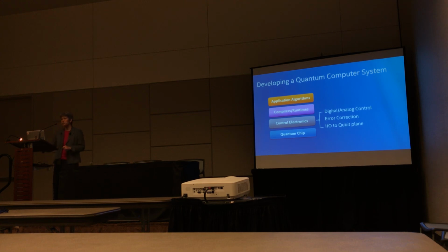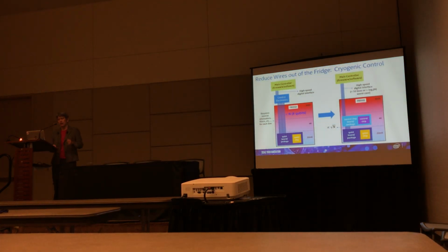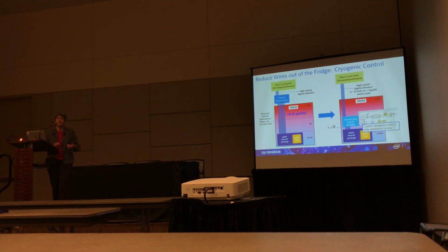So this I/O problem, there are many problems for qubit control, but the I/O problem is a big one. We, as a number of other quantum groups, are looking at bringing the control chip inside the chamber to cryogenic temperatures. The reason is that you need about 1 million qubits for a commercial device, and our qubits run at cryogenic temperatures, in a dilution refrigerator.